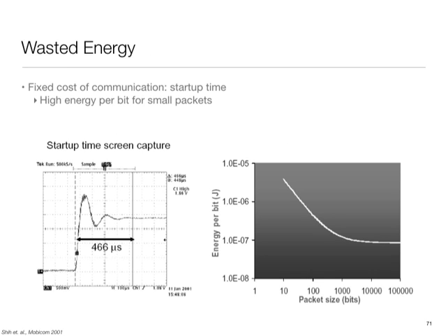One other thing which often causes a lot of wastage is the role some crucial parameters can play. So for example, take the issue of packet length, or more precisely, frame length. If you think about communication, your lower level device has something called the physical layer frame, which is sent over the communication link. Inside that is encapsulated your data packet. At the beginning of this physical layer frame, it has what's called a preamble. The idea behind the preamble is that using it, the receiver trains its clock and estimates the characteristics of the channel. Usually the preamble is a well-known, well-advertised bit pattern, so that when the receiver gets it, it learns how the channel is, and how the transmitter's clock frequency is related to the receiver's clock frequency, and so it does all this adjustment.